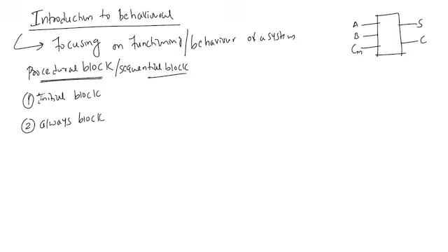The initial block is non-synthesizable, so we can't convert it into hardware. It will execute only one time, only one simulation time. Always means it will execute forever. So this is synthesizable, and this is non-synthesizable. This initial block we are using only in the test bench.